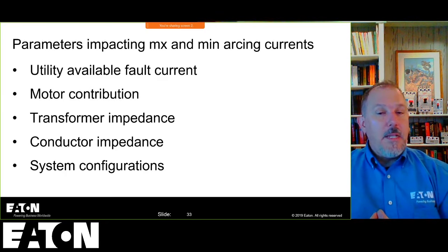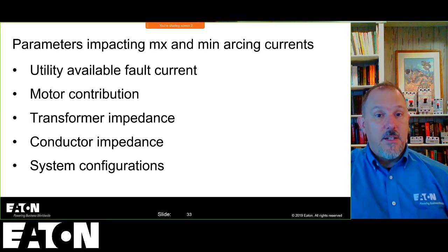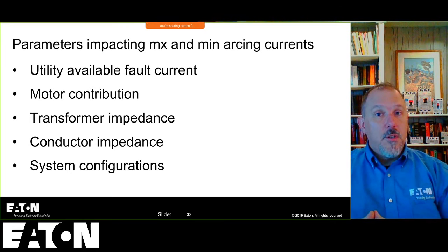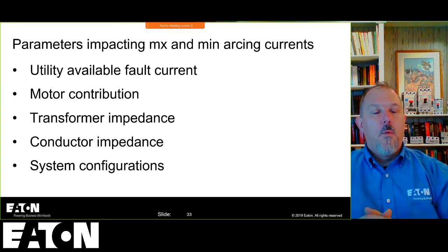So transformer impedances, we talked about this in the transformer class that we had, that the impedance that's marked on those transformers can be plus or minus 10%. So we have to include that minus and plus number to get both worst cases.